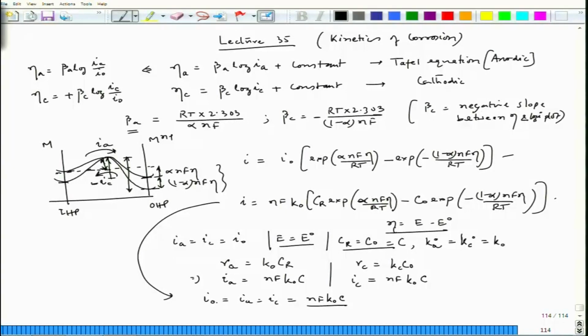So, then if I take this C out, then I am getting the same expression here, because this part is nothing but I0, is not it? So, we are getting the same equation considering both the routes. One was considering the rate equation, and then another one is the jump theory, that classical rate theory, where we are considering the jump of atoms due to the vibration of the atoms from one plane to another.